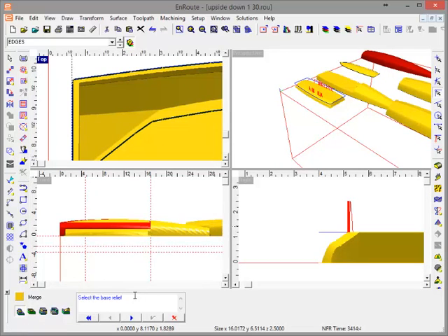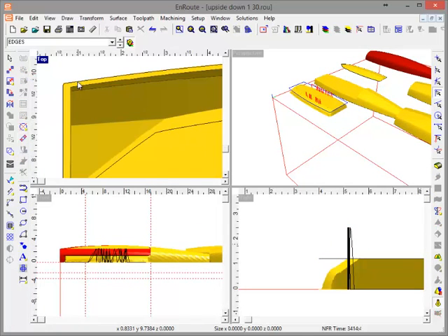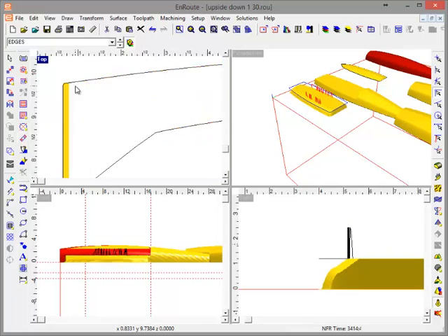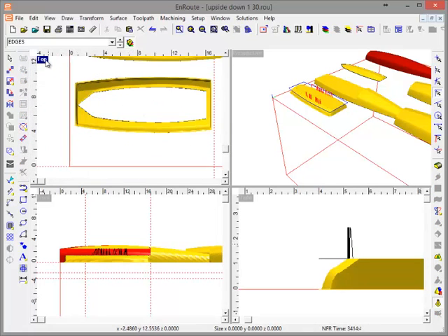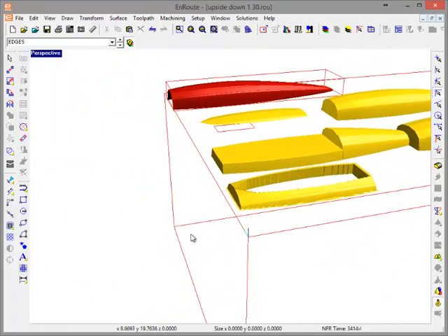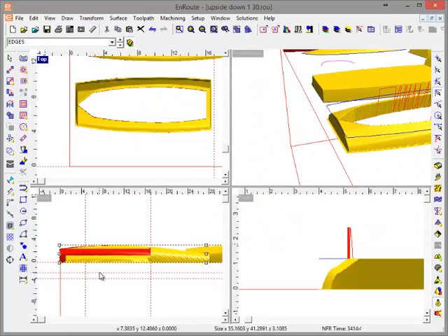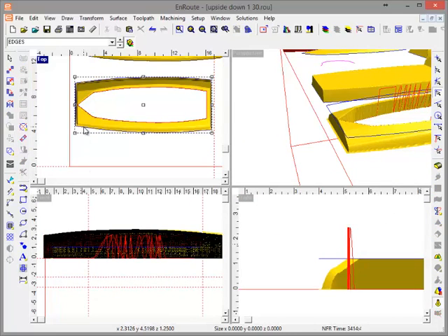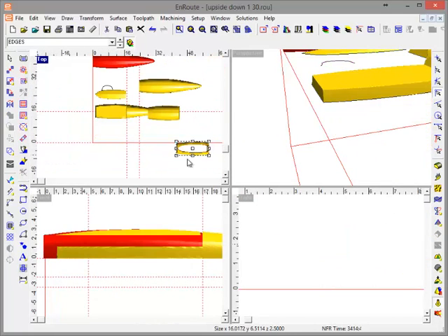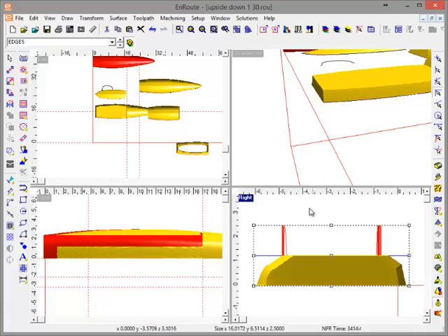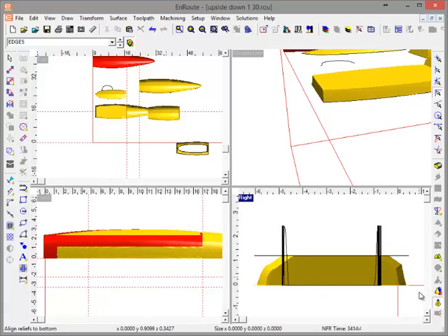Merge reliefs. Here's the base relief. Here's the one I want to add to the base relief. Check mark. Now if I did my job right, I should be able to delete that one and have this other piece as a hollow piece. All right, and yeah, there was some funky stuff going on with one of these geometries, but let's go here and look at this thing. This is a messed up part, so I'm going to get rid of that thing for now.